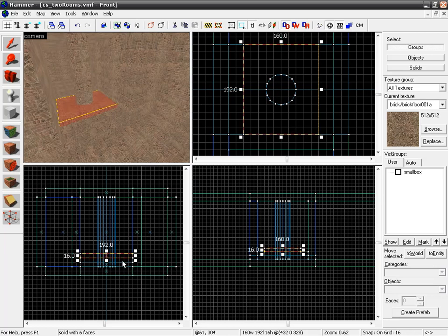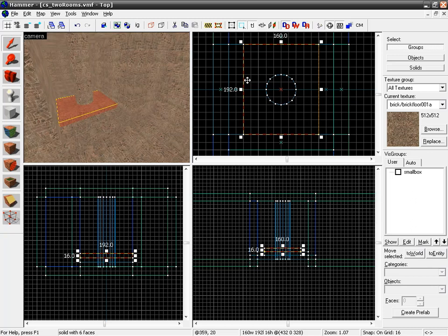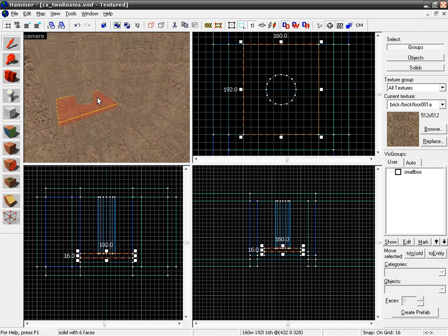Now, we also have far more cubes than we need here, so we'll just do some really basic optimization, and we'll take our lower steps, let's drag them in, shift click to replace on the other side, and the same on the floor. Drag this one in, only what we need, shift drag it. Now we have more brushes, but we don't have a bunch of brushes just stacked on top of each other that you're never going to see. Okay. We can also grab our cylinder and drag it up so it now rests on top of our topmost step, or landing.